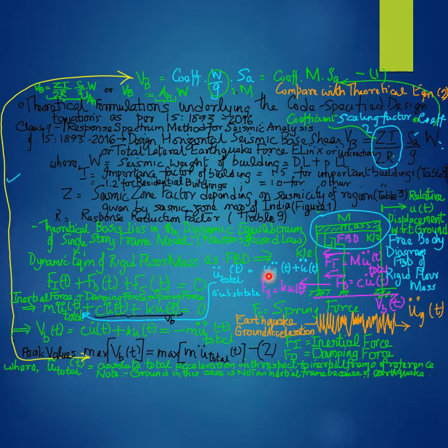together times the relative displacement of the floor mass relative to the ground, thus resulting in the dynamic spring force, since the relative displacement itself is a time variant function, a dynamic quantity. The spring force resulting from the multiplication of the spring constant or spring stiffness K and the relative displacement is also a dynamic quantity.